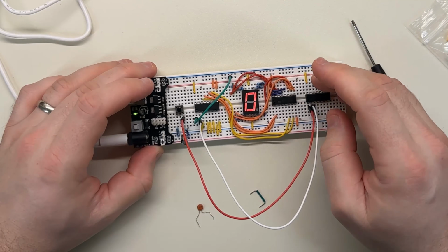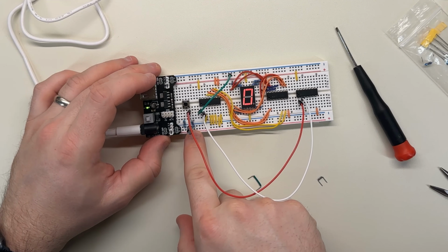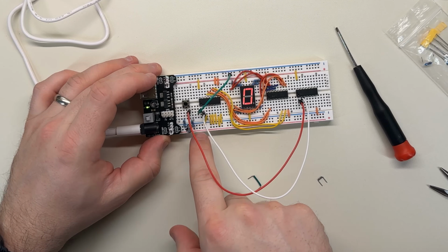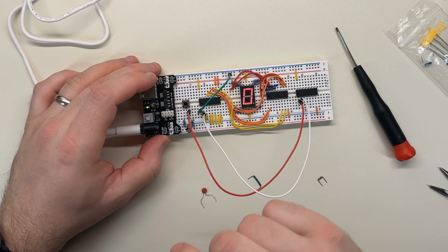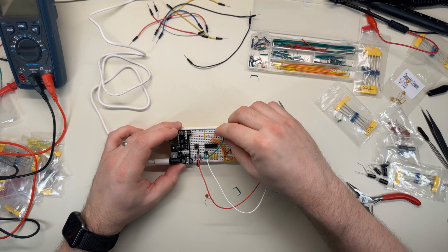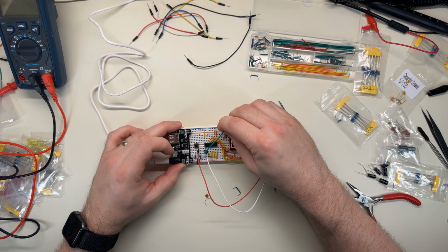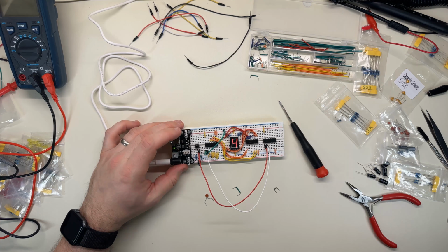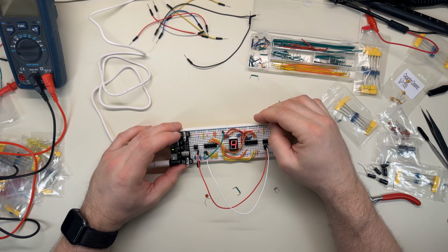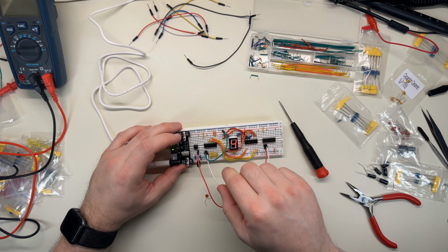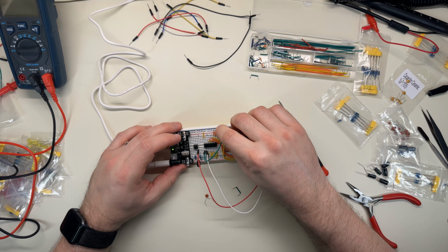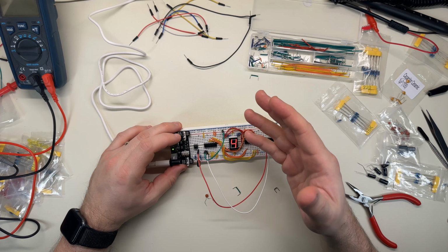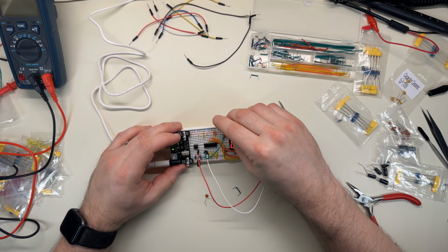That should mean that if I just hook up another circuit like this one, basically just another debounce circuit, on the reset pin, I think I can solve my reset problem where it should always start reset instead of at random garbage values. So I'm pretty sure that the way to hook that up is I need to have a high signal after the capacitor has charged up and a low signal initially.